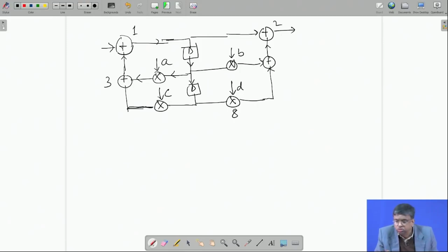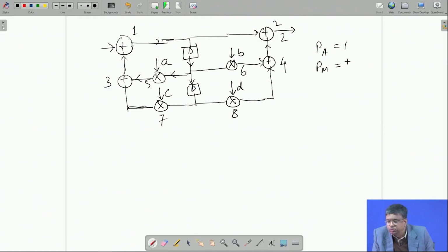1, this is 2, 3, 4, 5, 6, 7, 8. This is a conventional digital filter. All of us know the direct form 2 digital filter. Pipeline latches PA equal to 1 as before, multiplier requires 2 latches. N is 4, that is 4 adders to be replaced by 1 hardware adder unit, and 4 multipliers to be replaced by 1 hardware multiplier unit, very much like example 1 which we considered earlier. And the schedules are also the same as we considered last time.